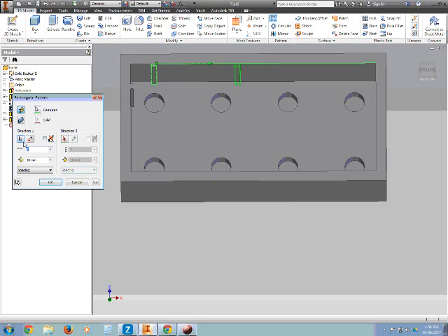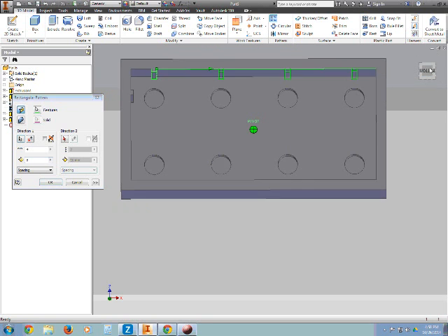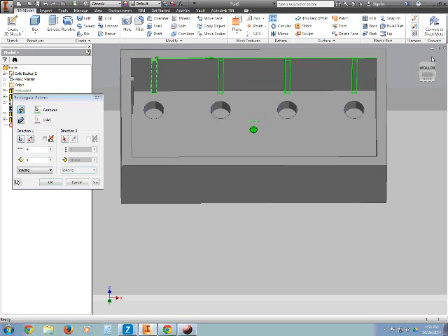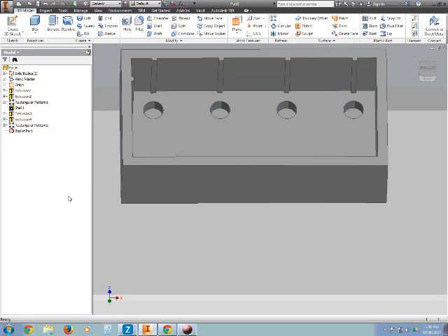So we want 4 of these, 8 millimeters apart. And we probably could, if we had this distance across here, do this other set. But we need the planes on here for assembly anyway, I believe. So we're going to go ahead and mirror them the way I had originally planned. We'll go ahead and click on OK.